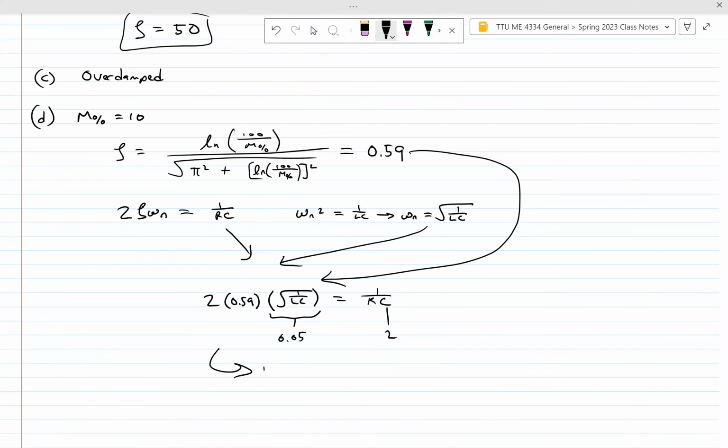What type of resistor do we need in this circuit to make it underdamped, where if we put in a step for our voltage, we would get an overshoot of 10%? You guys want to solve that equation for C. That sounds like a lot of work. You could do it, absolutely. I think replacing the resistor would be the easiest.